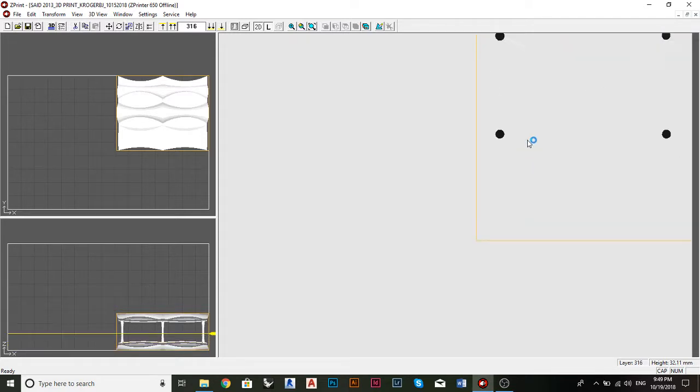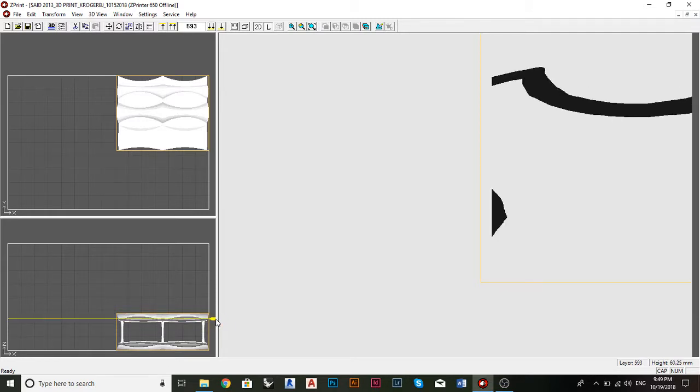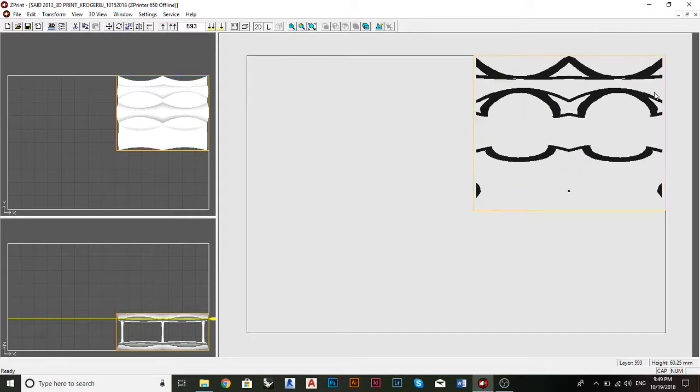So this solid object, for example, right here I'm kind of through this surface port right here. This is one whole layer that it is going to print. So it's going to go all the way through here, and it's going to fill all that in. So you want to be aware, if you have a whole square that's filled in like that, black, that's just going to take forever to fill through. So you just want to maybe shell it out, kind of remove some material, which will also reduce the cost.